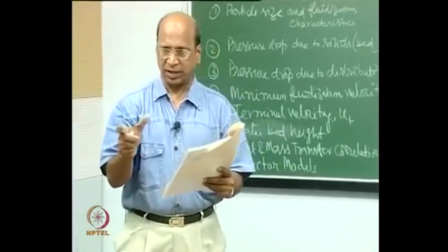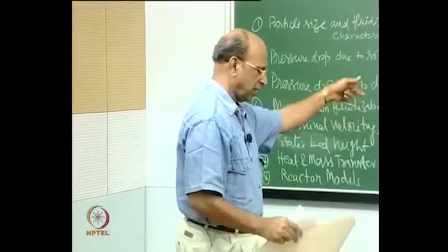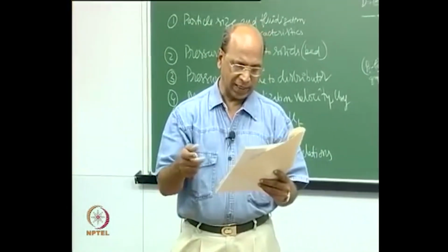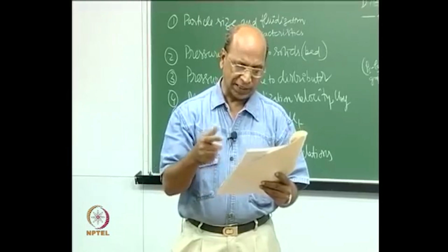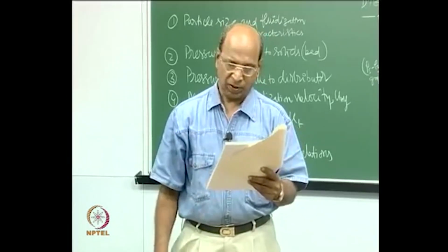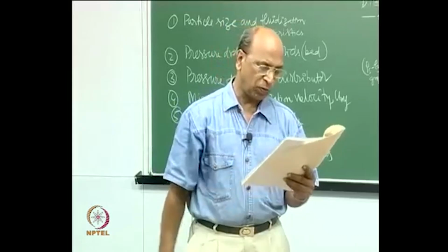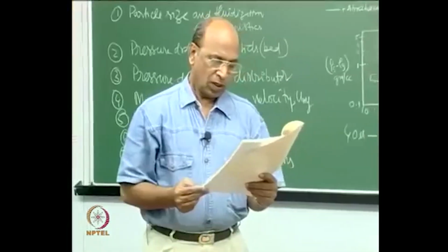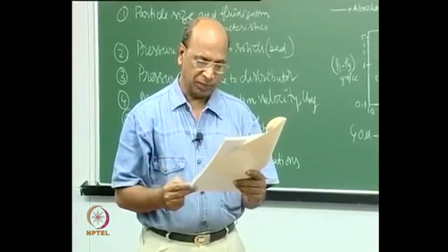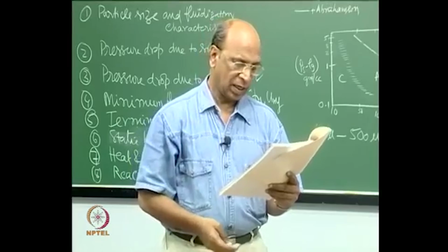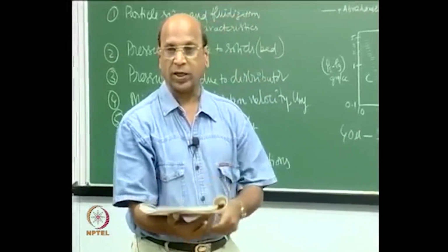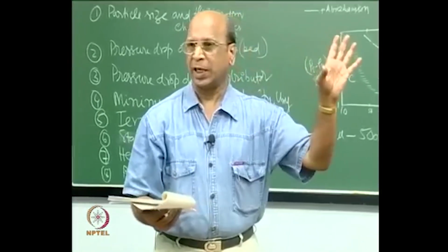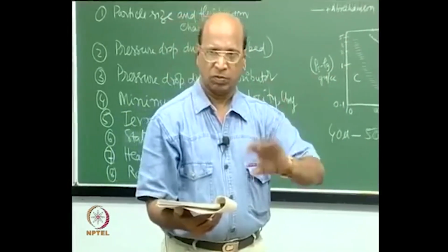Okay, that is the normal size range, but there you can see more than that also. These are the typical group: sand-like particles with a size range of 40 microns to 500 microns and a density range of 1400 to 4000 kg per meter cube. These solids fluidize well with vigorous bubbling action and bubbles that grow large. Particles similar to sand, whatever particles you get similar to sand.